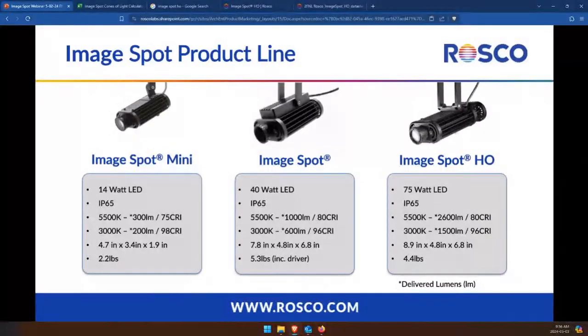The primary difference is it uses an external driver to free up more space for heat sinking. So the body itself is the same as the high temperature ImageSpot, or the ImageSpot HT, which also has this extended body for heat sinking. It's not listed here. We'll chat about it in just a second. The difference with the integral driver removed is that it provides more surface area to passively cool the fixture during operation. So again, no fans, and it also provides a really clean aesthetic without that driver on top. The high output LEDs are the same CCT as the rest of the product line.